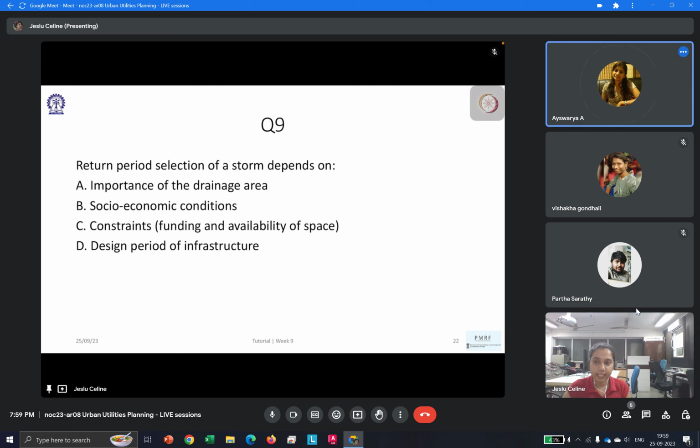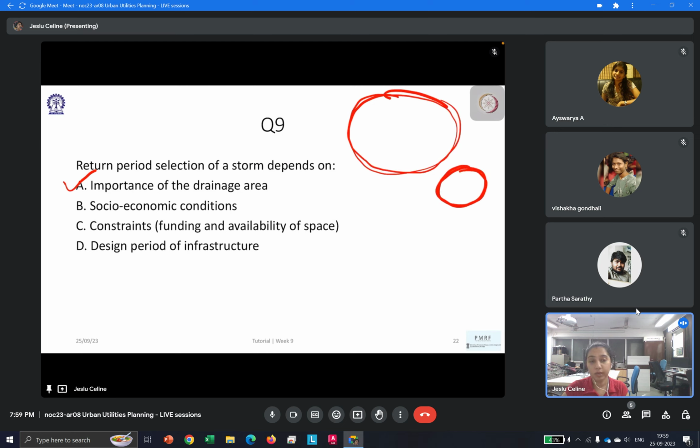Yes, ma'am. Why is it important? Because if you have 2 drainage areas, again, what is return period? You need that much intensity of rainfall to repeat after that certain interval. So if it is a small area, then you can say that I might get an intensity I, whereas if it is a large area, it depends upon your partial area effect also.